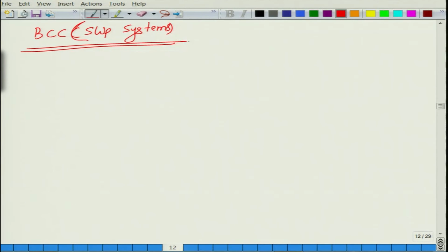What we have done in this lecture is that we have invoked the concept of slip systems. A slip system consists of two entities, the slip plane and the slip direction. The slip plane is the plane on which the planar density is highest. In a close packed system, it is the close packed plane. So, for FCC it is the 111 type of plane, for HCP it is the 0001 type of plane, but BCC and simple cubic structures do not have a close packed plane. In that case the highest density plane is the slip plane, and the slip directions are close packed directions, or directions with highest linear density.